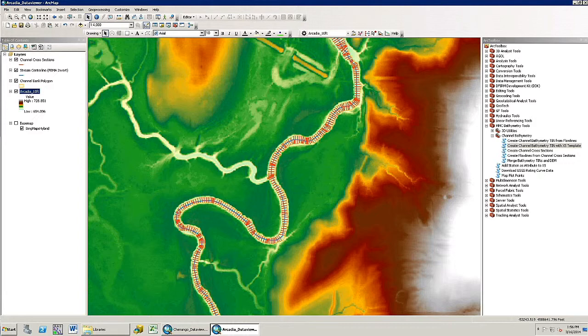This tool is step 2 of 3 of the Channel Bathymetry Surface Development workflow if you are designing the channel from a cross-section template. At this point, step 1 is finalized. Channel cross-sections were created from the Create Channel Cross-Sections tool, reviewed, and altered if necessary. This tool will develop a channel bathymetry TIN from one of 7 options.